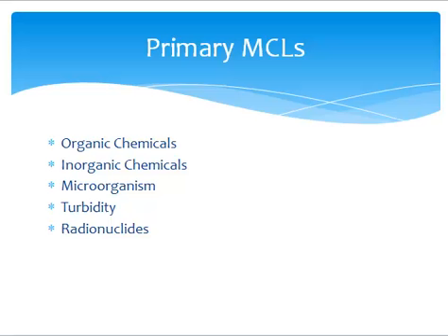In regards to organic chemicals, water supplies must be tested every 3 years. Inorganic chemicals, or those without carbon, must be tested annually. Because microorganisms can cause issues with public health, coliforms must not be found in more than 5% of samples in a month's time. While we often think of turbidity as an aesthetic problem, particles in the water can shield microorganisms from disinfectants. Thus, turbidity must be constantly monitored. Radionuclides are also monitored in public water supplies.